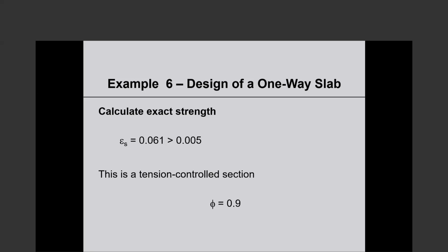So my question is, when you say the beam's capacity was checked, why didn't you include the slab in the first place? That's part of the beam. Why would you even check without the slab, without the overhanging flanges?